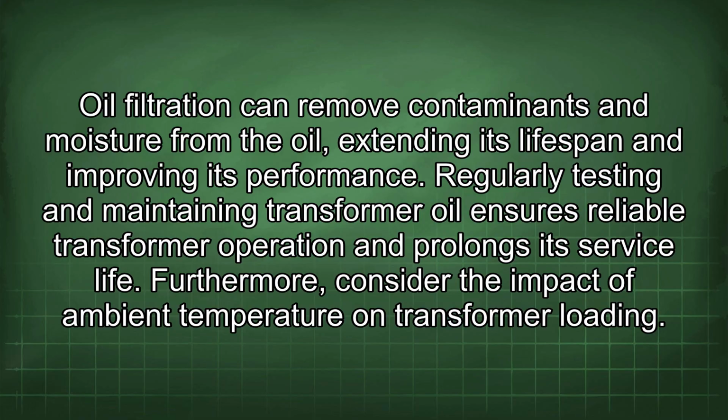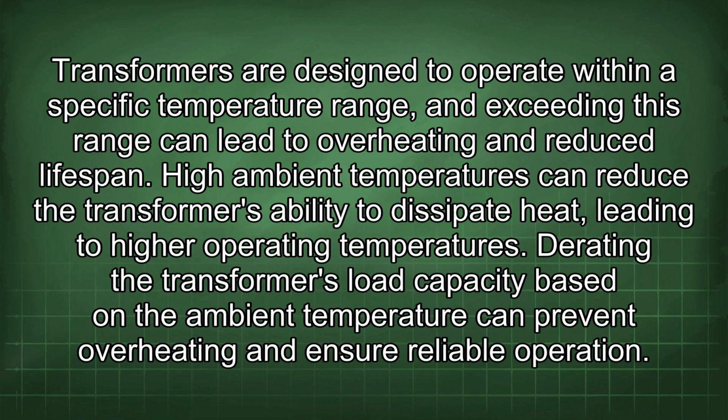Furthermore, consider the impact of ambient temperature on transformer loading. Transformers are designed to operate within a specific temperature range, and exceeding this range can lead to overheating and reduced lifespan. High ambient temperatures can reduce the transformer's ability to dissipate heat, leading to higher operating temperatures.